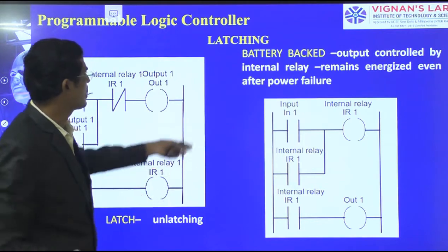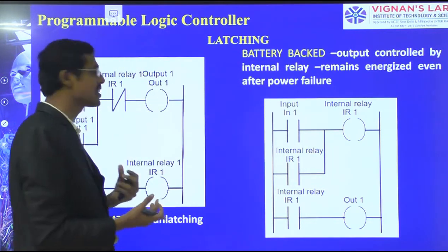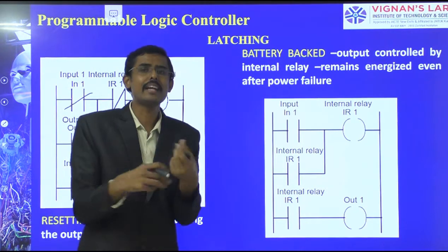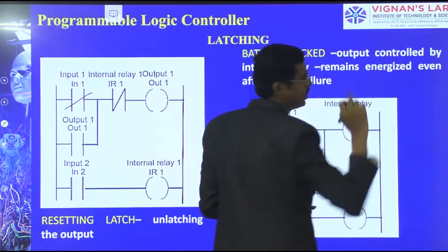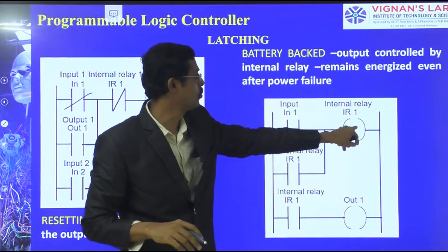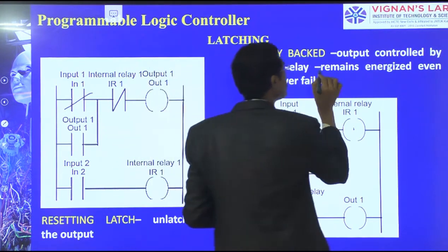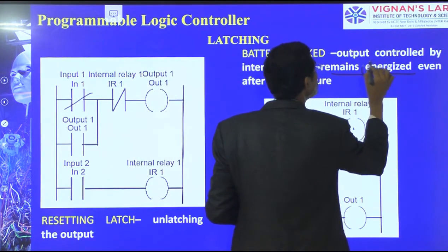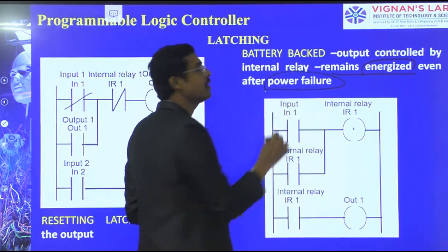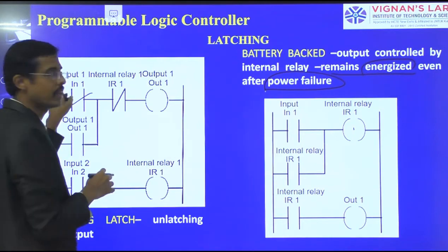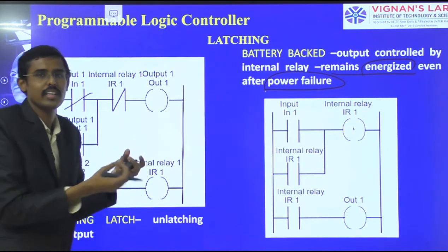Some similar patterns. Now, battery backup: I am replacing the term resetting with the term battery backup. It is a latching process only. See, the output is controlled by an internal relay, which remains energized even after the power failure. It means nothing but a push button. Here we have removed it, but that is still called latching. I am calling it a battery backup.